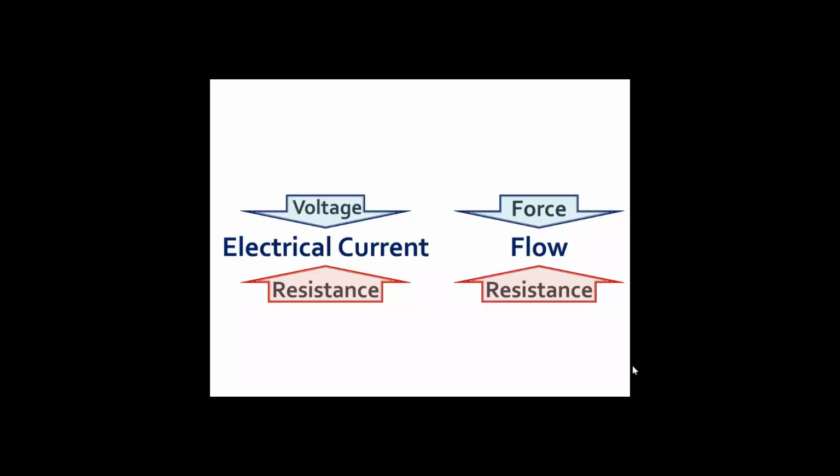So in an electrical system, a good example would be in a thunderstorm. If a bolt of lightning hits the power lines and sends a surge into your house, the plastic and rubber insulation on all of the conductors running through your home have a rating usually of 600 volts. If that voltage is exceeded, and they measure the ability of a material to insulate electrically, they call it dielectric strength.